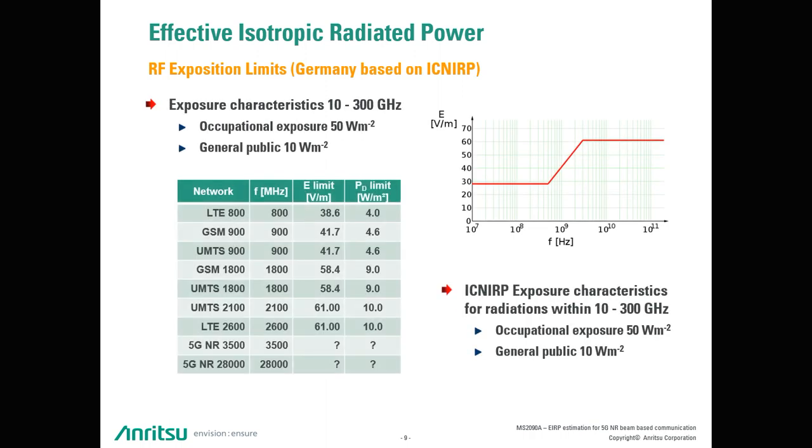In mobile radio systems like GSM, EDGE, UMTS, Wi-Fi, WiMAX, and LTE, the peak value of the transmission power differs significantly from the root mean square value. Not so in classic GSM. Here a modulation with a constant envelope is used.